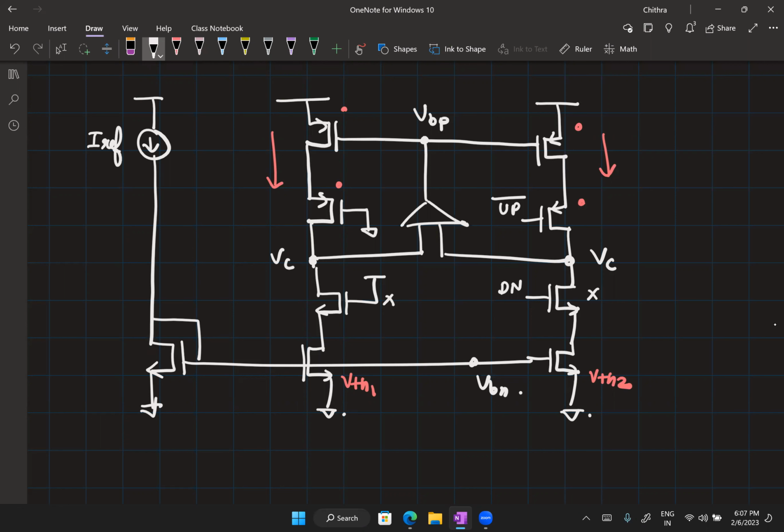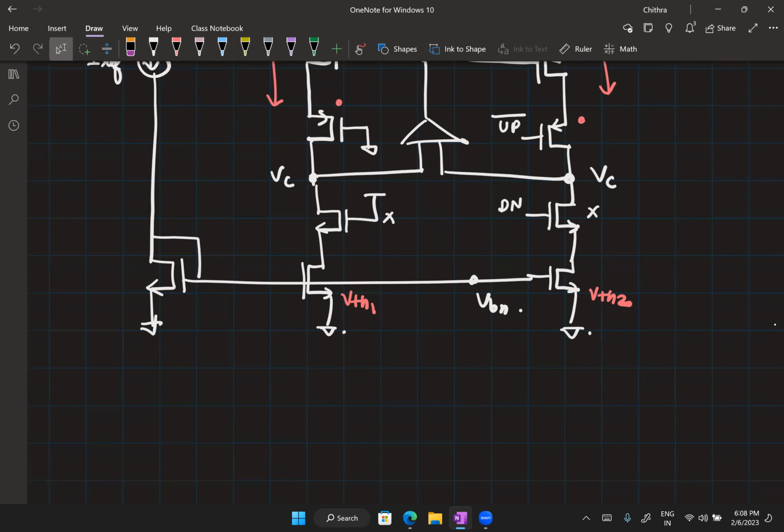And this current mismatch is not exactly predictable. We don't know the exact value with which the current is going to be mismatched. Now, this is different from when we had VC being different, the VDS of the transistors being different. If we know the difference in the VDS, which we can find out from simulation, we will be able to exactly predict by how much the currents are mismatched. This is different. So this is due to random mismatches in the transistor properties. And this being non-deterministic, we will now have to deal with statistics, right? Statistics of by how much the VTH is going to vary.